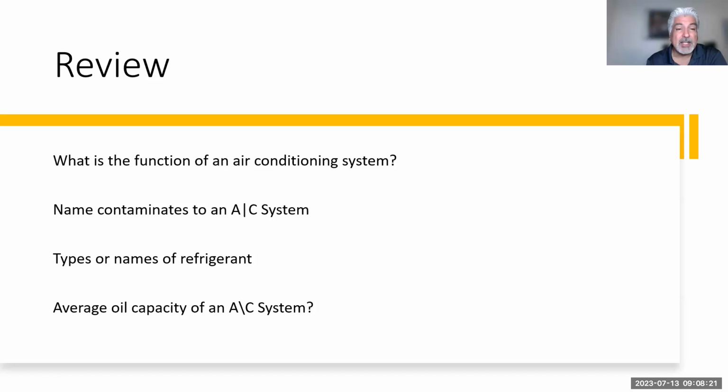So we talked about the vacuum pump, and we told you about the test. I was actually going to search for my mason jar that I mentioned in part one about testing a vacuum pump, to see if it boils water. We talked about that. In this case, you definitely want to test your vacuum pumps, because if it's not actually boiling or getting the moisture out, then we're going to have a problem. And those of you that live in high humid areas, this is a problem because you need to do more maintenance on that vacuum pump. So we'll review that as we move along. But hopefully by next week, when I teach part three, we'll have the jar ready. I'll have it showing to you how we do it here in our area, because I can't find my jar, but that's another story in itself.